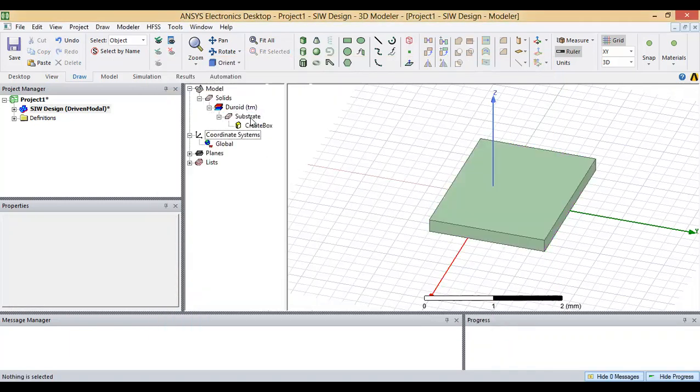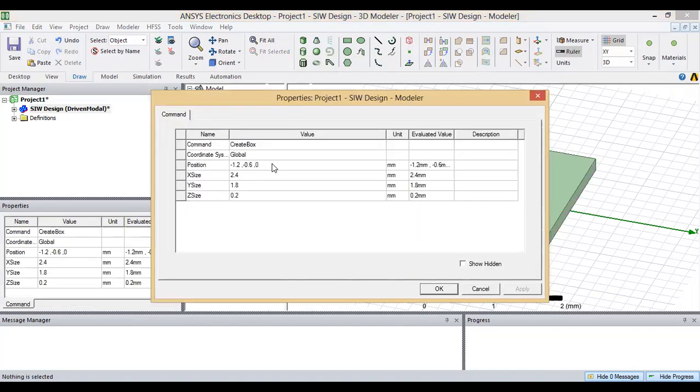Now we have made it, and now we need to set its length and width. Considering it is square, the length and width will be 34 by 34. So we'll assign the coordinates -17, -17, and we'll start it from 0 millimeter. This one will be 34 mm and 34 mm. The height I can give 0.787.